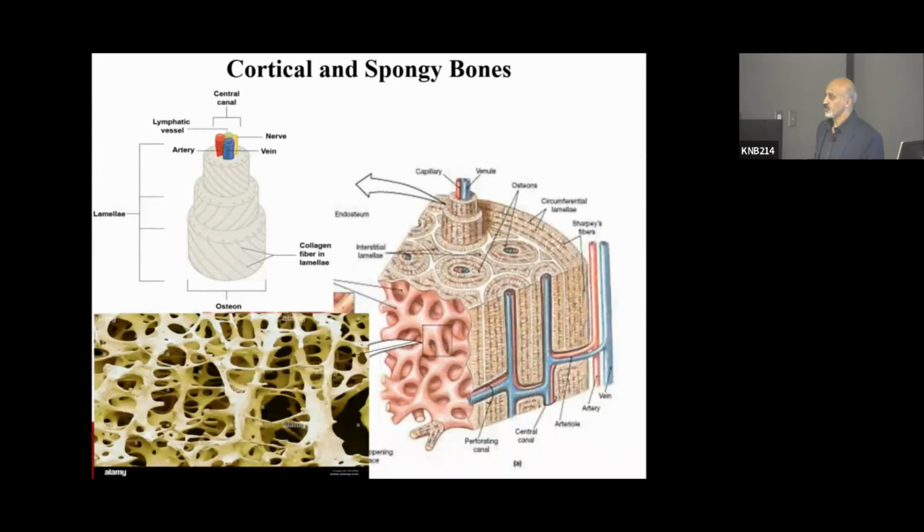Okay, here on the left-hand side, you see a stress-strain curve. We applied, let's say, load on a piece of bone. When we increase the load, the stress would increase as well as the strain up to this point, which we call in mechanics the yield point. If I load it, then unload it, the loading and unloading curves would be quite the same. So if I remove the load, I would go to this point, which means that if the stress is 0, then the strain is 0.